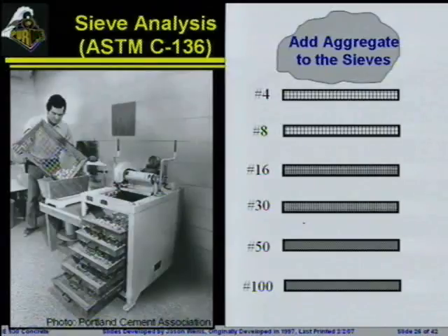Now this is really what you guys paid the money for today, because this is one of the best animations I've ever created in PowerPoint. Here we see a gentleman who's very excited about running the sieve test, the ASTM C136 test. Here he's doing this on coarse aggregate, so you get a little bit of a scale of the size of the sieves. And basically what's going to happen is a large volume of this aggregate is going to be placed on the top of the shaker.